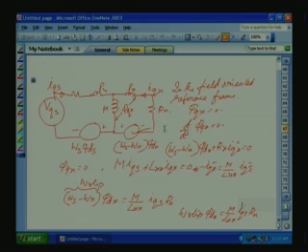So, from the rotor circuit, d by dt psi QR is 0, then the voltage coming across the RR is the rotational voltage. So, that we equated. Then we found the IQR in terms of IQS, that is from the flux equation. Then we found omega slip is proportional to IQS. Okay, so under field oriented control, omega slip is proportional to IQS, and we know that for a motor the torque is proportional to slip.